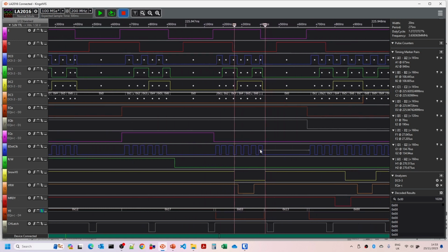Again, 3 doesn't require any change to the clock timing, so this fits in neatly as well. And if we were to look at all of these values, I've gone through all the values and cycled through them all and checked to see that they're all within the bounds. So hopefully we shouldn't have any issues where the video access is interfering with the latching of data to go into the video display output.